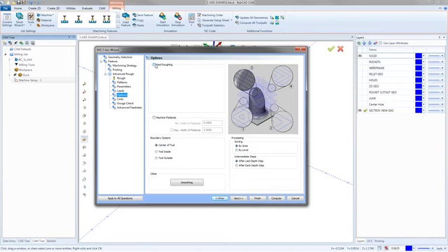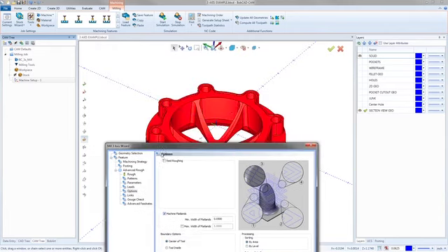The second one is going to be the one that looks at what's been cut and now only gives us a cut where the previous tool couldn't fit. So in this case, my first advanced rough, I'd ignore the rest roughing. I can turn on the machine flatlands, but I still have 30 thousandths of material showing up. So really the only time the machine flatlands is going to be beneficial to me, or it really is always beneficial. But what ends up happening is right here.